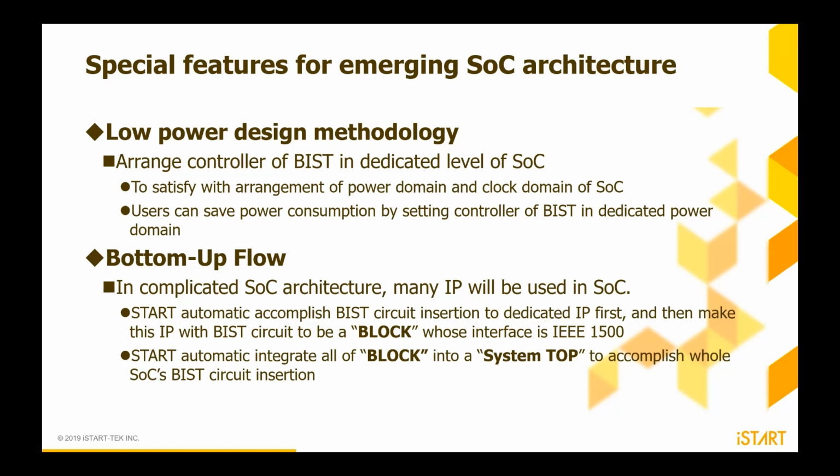Next I will introduce 2 special features of our SoC architecture. The first one is the low power design technology. For low power design, we can arrange the BIST controller at a dedicated level of the SoC, so the designer can assign the controller to the level you want to specify.